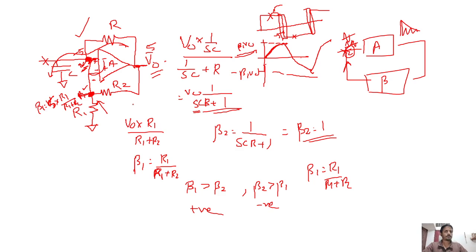Sir, one more thing I want to mention is when we have capacitors in the circuit, like feedback networks, how to determine the feedback? Whether I can take just V naught as DC, or anything else? It depends upon the frequency. For example, if I give simply a DC voltage, definitely the capacitor is open circuited.